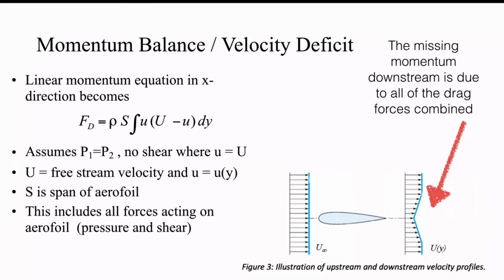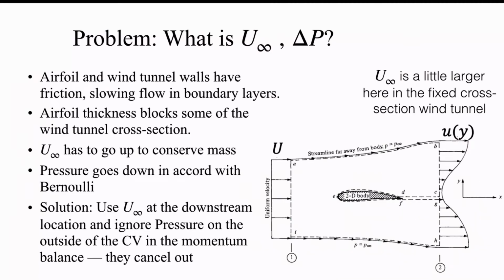We've already found out how we can estimate the pressure drag. From that, we could pull out what the other contribution was, the skin friction drag. Possible problem for those of you who remember from first fluids, we had to account for all the forces when we did a momentum balance. And we had pressure forces. So what if there was a difference in pressure between the front and the back? That pressure difference isn't there in an open flow with no boundaries.